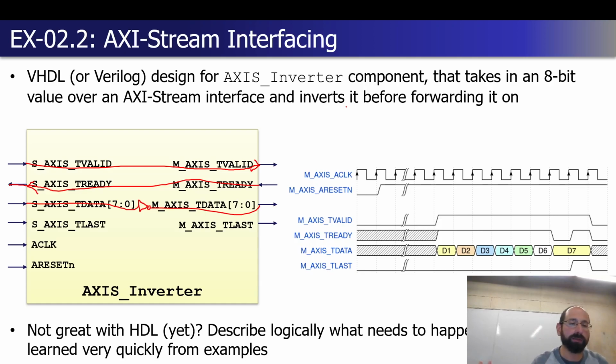And it can be a little subtle because there's no guarantee that everything is working at the same rate. They're not nicely synchronized with each other. We will eventually get to a point, and even in MP1 you'll get to the point, where render output is going to be significantly slower than viewport. Viewport is doing very little work, right? Take an address, change the address is all that viewport is doing. Takes a couple cycles, or do it in one cycle if you can get it to work. Render output is also not doing that much work, but ultimately it's writing pixels to the frame buffer. That could take 200 cycles.